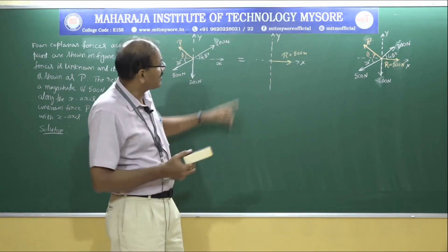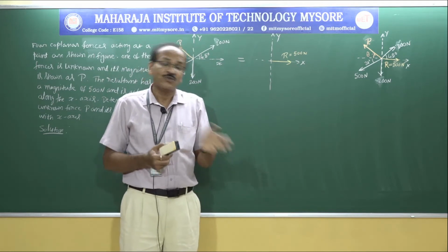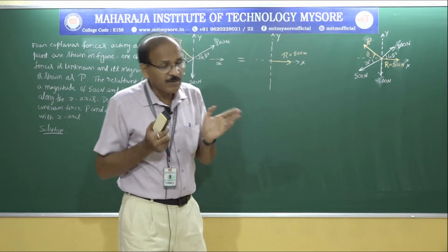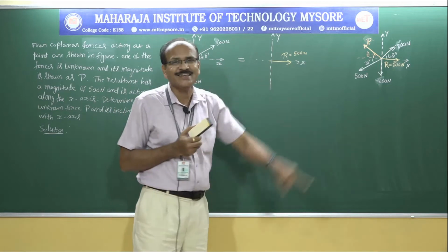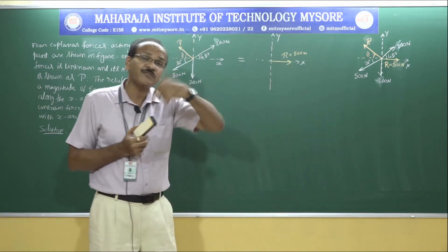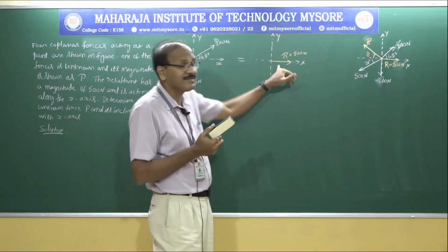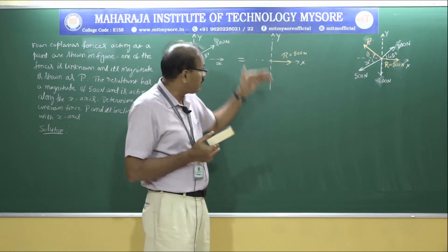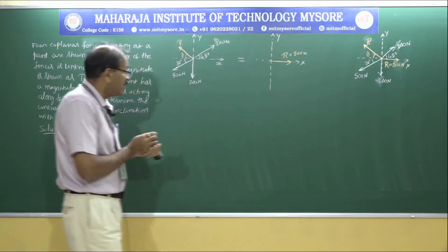So in this case the resultant is acting horizontally. So sigma Fx, that is the algebraic sum of the components of all the forces in the x direction, should be equated to the resultant. As far as sigma Fy is concerned, that should be equated to 0 because this resultant does not have a vertical component. So those are the steps I am going to do to solve this problem.